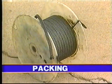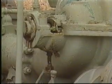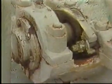Packing is soft and pliable, usually made of cotton, asbestos, or flax. It's woven or braided into a continuous square-shaped strand. Generally, it's coated with graphite or Teflon for lubrication, and since it's softer than the shaft, there's no damage to the shaft when it rubs against the packing. Still, additional lubrication is needed to cut friction to a minimum. Some fluid leaks out of the stuffing box. That's normal, and even good, because it provides more lubrication between the shaft and packing.